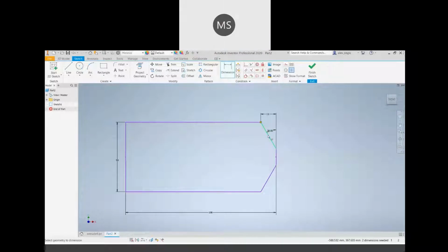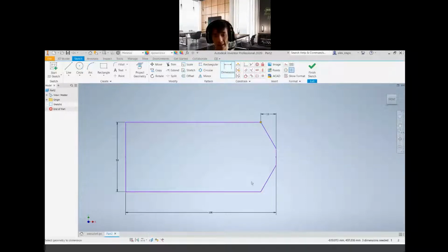So can you explain the angle one again? Yeah, angle. Dimension. You have this inclined line. Click on it once, and then the second line, this vertical line. So you have this option here, right? Or you can actually turn it into this form. Angle, 2 lines, so 1 and 2. Okay, I give you a minute to try this one out.